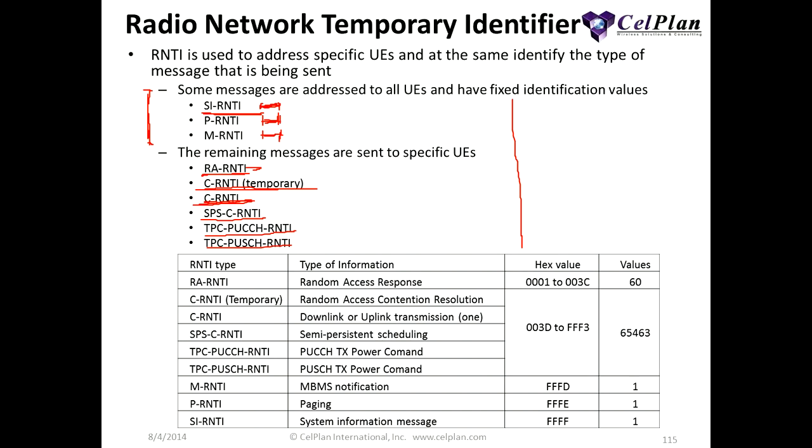So you can see that a single UE has several identities that vary by context, and it has to blind decode every CCE position inside the relevant search space with each one of those identities. And this is one of the reasons that batteries are consumed a lot.